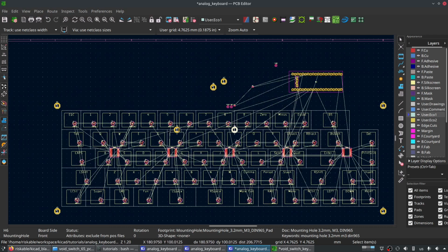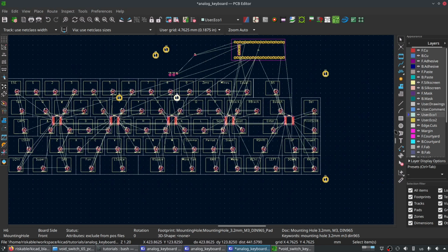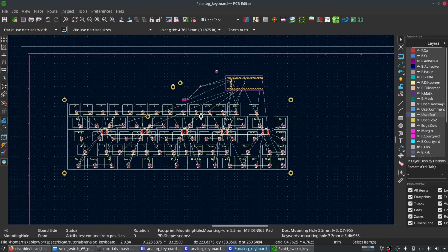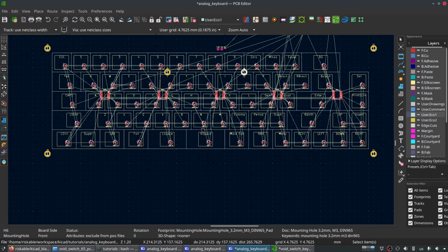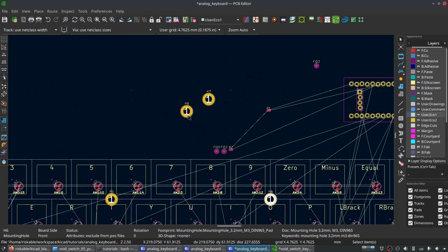The reason why we're doing it like this, for reference, is like, why is it here and there and not in the perfect center? It's because not many people have a 3D printer that can print an entire keyboard case across the whole thing. In fact, let's move this one over a little bit. There. Right, so it's the approximate center. That way, when someone's printing out in halves, this half will have the screw hole in it, and the other half will have its own screw hole. That way, we don't have to cut it in half. We're not doing much trouble when we're printing things in sections.